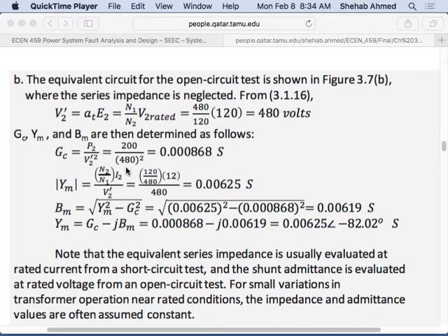I put some voltage on the secondary side. It will be ramped up by the turns ratio on the primary side. Take that voltage, place it across that impedance, and some current will flow. They gave us the value of power in that case, and we know voltage, right? Did they give us anything else? That's it, I think. They just gave us power and voltage. So if I know real power, I'm placing this voltage across an impedance. This impedance is a combination of an R and an inductance. If I know real power, this real power is being dissipated only in the resistance, right? I know that for a fact.